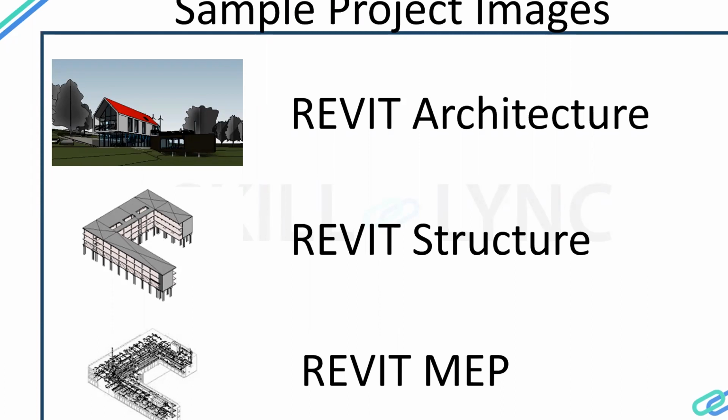Please note that this template needs to be prepared with the help of the BIM coordinator or the BIM manager, because those people have very good knowledge about the BIM standards and related codes in their country. Each and every country has individual BIM standards, and those standards need to be followed in your Revit model. For example, some countries follow imperial, some countries follow metric. Okay, so the template we start with first.